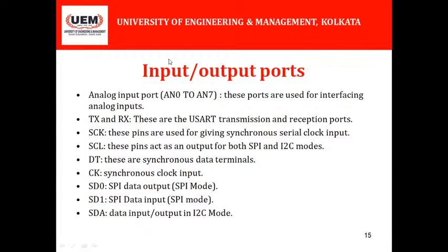Input output ports, analog input ports are denoted by AN0 to AN7. These ports are used for interfacing analog input. TX and RX: TX is for transmitting data with the help of the universal synchronous asynchronous receiver transmitter peripheral, and RX stands for receive data, which will receive the data from the USART.